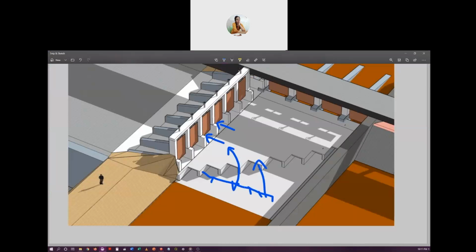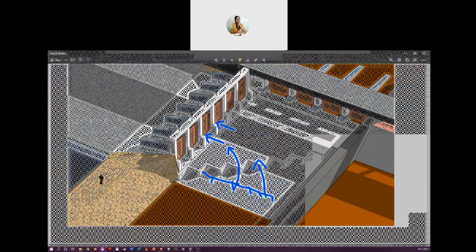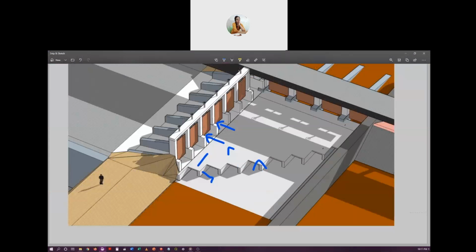Once we adjust the tunnel lengths so that this tunnel is the longest and this tunnel is the shortest and so on, then because the water velocity is in this direction, a major part of the lower portion of the flow will enter these tunnels, and along with that, sediments or the silt will be trapped inside these tunnels.